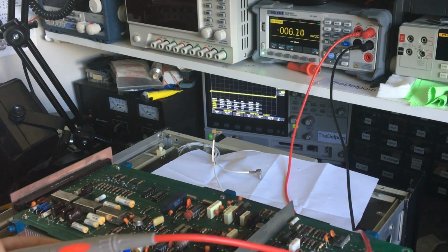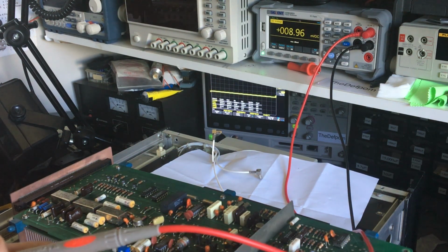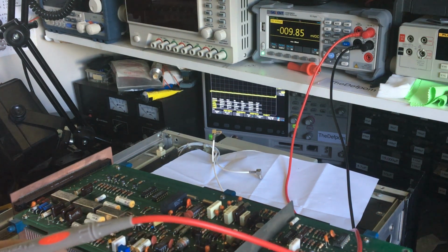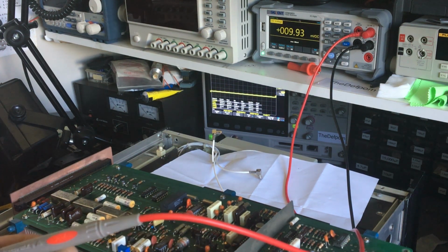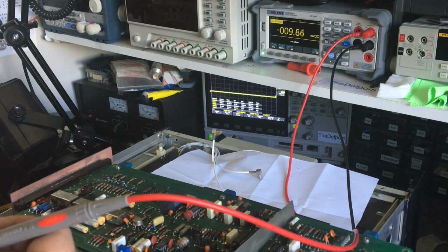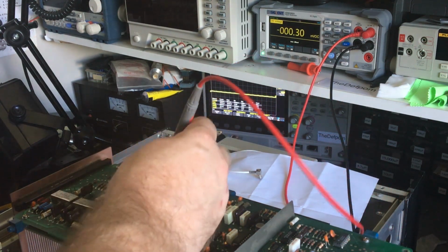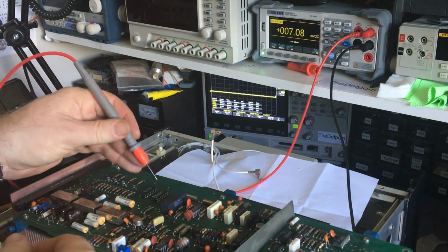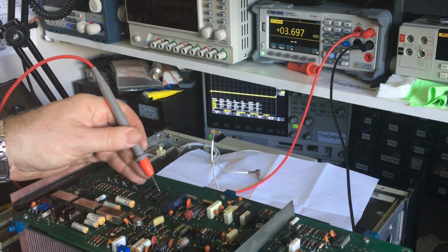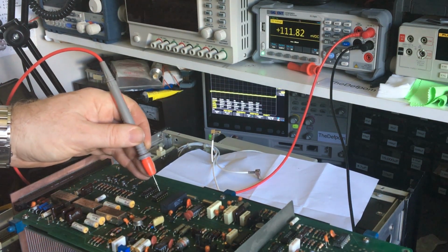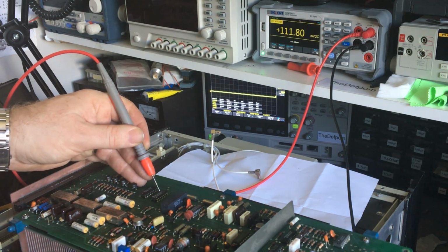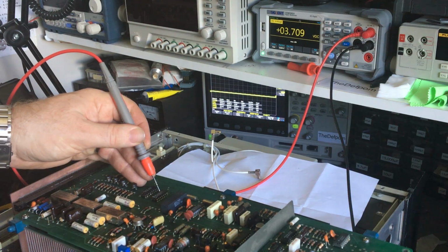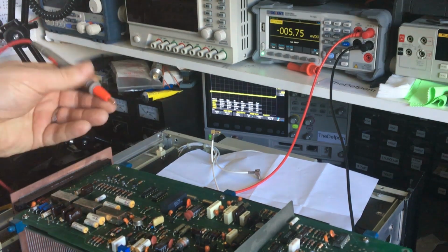Now I need to look at the next input, which I'm going to do as pin 9, 10 and 8. 9, 10 are the inputs, 8 is the output. So that's 9, which is high, that's on 100 Hertz. And on 1 kilohertz it's off, 10 kilohertz it's on, 100 kilohertz it's off, 1 megahertz it's on, which is correct.